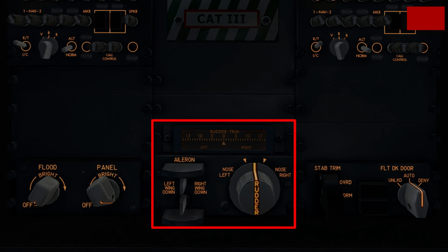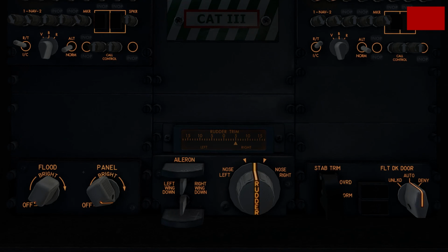Now, just like the pitch trim system we explored earlier, these trim systems control the roll and yaw characteristics of the aircraft, but are normally left in their normal zero position, wherein the controls are neither veering to the left or to the right and are perfectly straight. However, in the case of an emergency, such as an engine failure, asymmetrical thrust gets produced, as the working engine slowly turns the aircraft in the other direction. In such a case, pilots can align the rudder and ailerons to constantly be facing in a particular direction to zero this rolling and yawing motion out, and for the aircraft to fly straight as planned. The stabilizer trim switch is again related to the pitch trim system, but it's not simulated in the ZIBO 737.